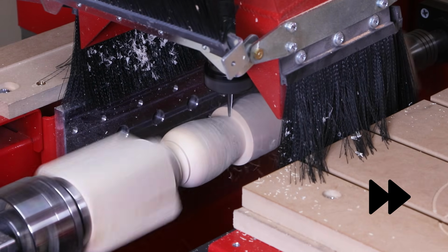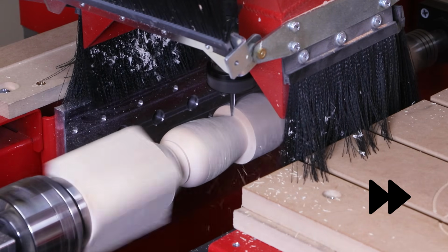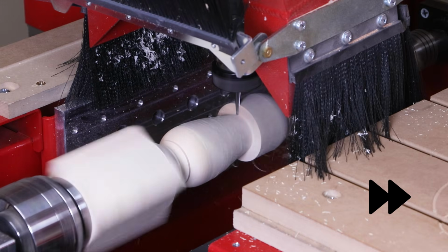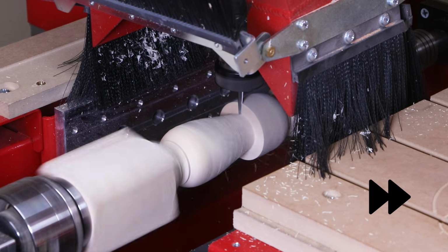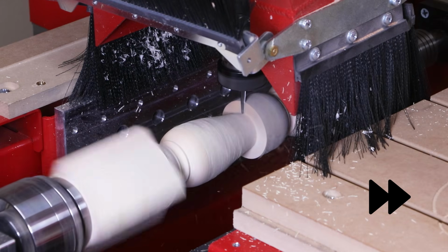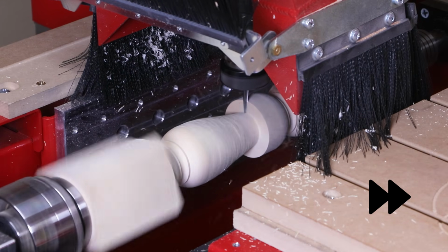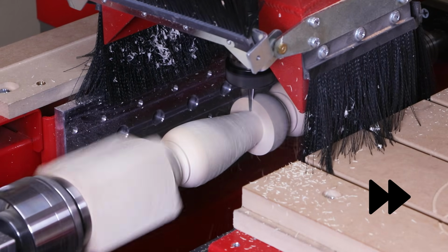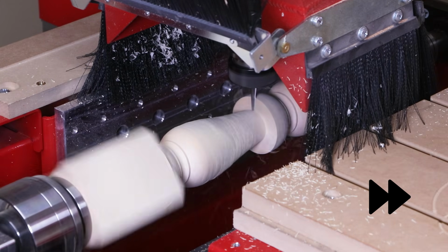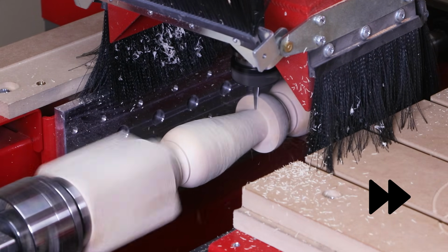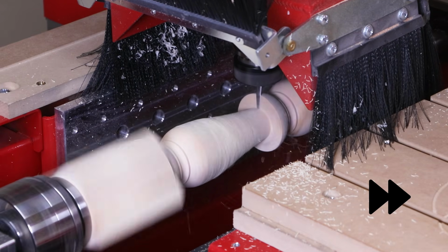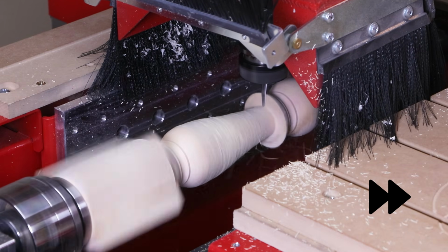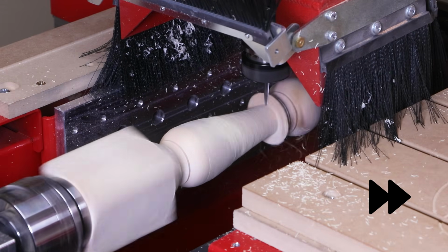In other videos, we'll also show how we need to rough out additional material before cutting this vector turning process, because we don't want to put too much load on the ball cutter. This is only taking about 1/2 of an inch of material at the deepest section, and these taper ball cutters can do that all day. Even though we're using a small 1/8 inch ball cutter, this whole process took just less than 5 minutes to turn. The ability to take a 3-axis G-code toolpath, a profile toolpath, and convert it for this vector turning is a game changer when it comes to this contour design effect.